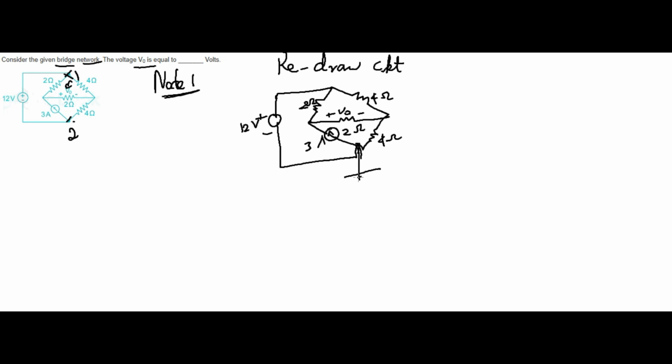And in the redraw you have to make the small ground. Okay, so node 1 represents V1. First you take this first one. So V1, what is the exact connection of the voltage? 12, is it? So for V1 you have to eliminate the 12. If you consider some point as that voltage, you have to eliminate the remaining voltages. Okay, so exact match is here, this one. V1 minus 12 divided by what's the connected resistor? This is 2, because in between these two, the 2 ohm is the 1. Okay, so you can make it 2.